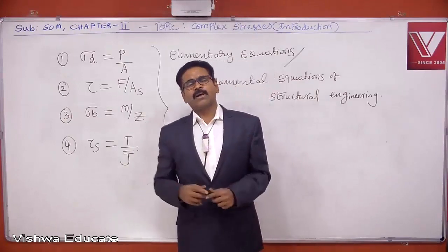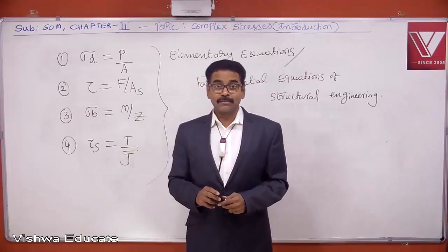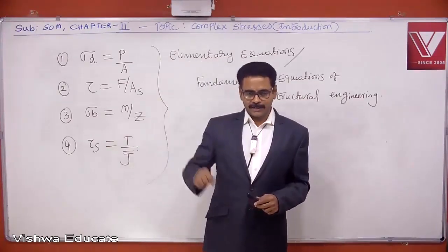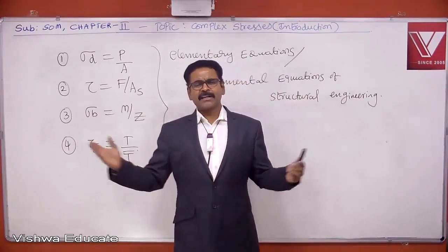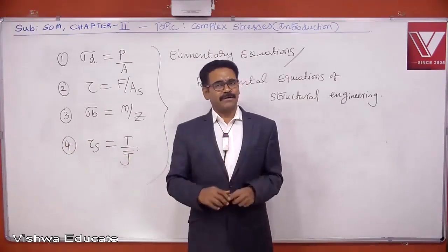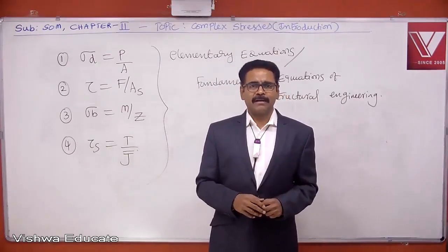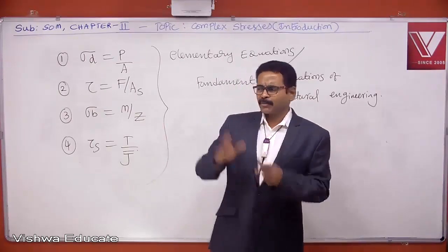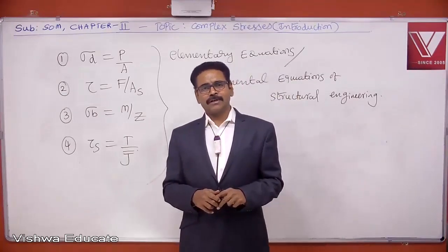If the major principal plane is safe, nothing is going to happen to the entire structure. You should not blindly worry about every plane. Identify the angle of the major principal plane and always monitor that particular plane.